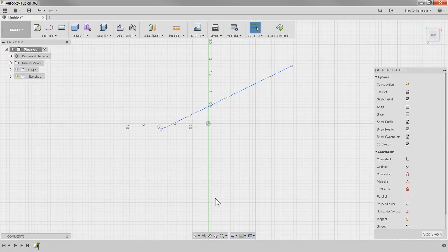That also works with other things. Like if you have a fillet on a part and you hit Delete, you will delete the fillet, but Fusion is smart enough to try to solve itself. So that was three: L for line, Escape, which you got to know about if you haven't already figured it out, the Delete key to delete items, and then of course also Control Z, which is pretty universal.